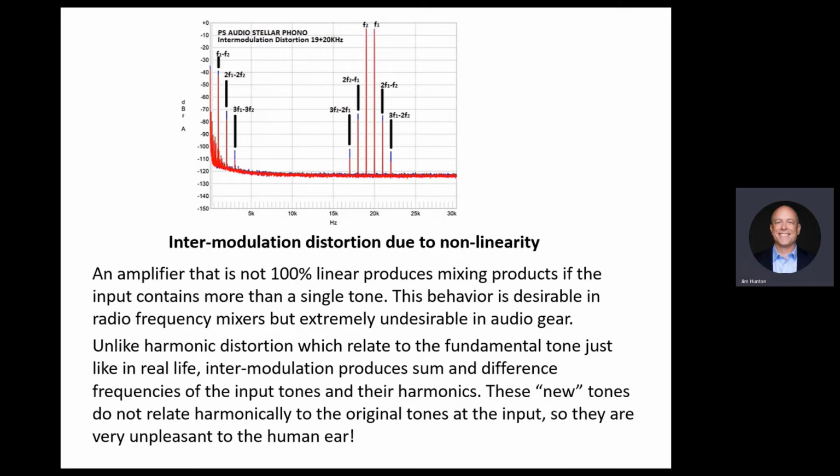Those signals mix because of this nonlinearity. The levels between the two of them, when they sit on top of each other, change. You get some funny voltage swing, and that funny thing comes out distorted on the output, and the distortion is nonlinear. So when you do that with several tones, you end up with combinations of those tones. So you get first plus second, which is going to be around 30 kilohertz. We don't care about that. But first minus second is 1 kilohertz in this case, and we do see a strong 1 kilohertz.